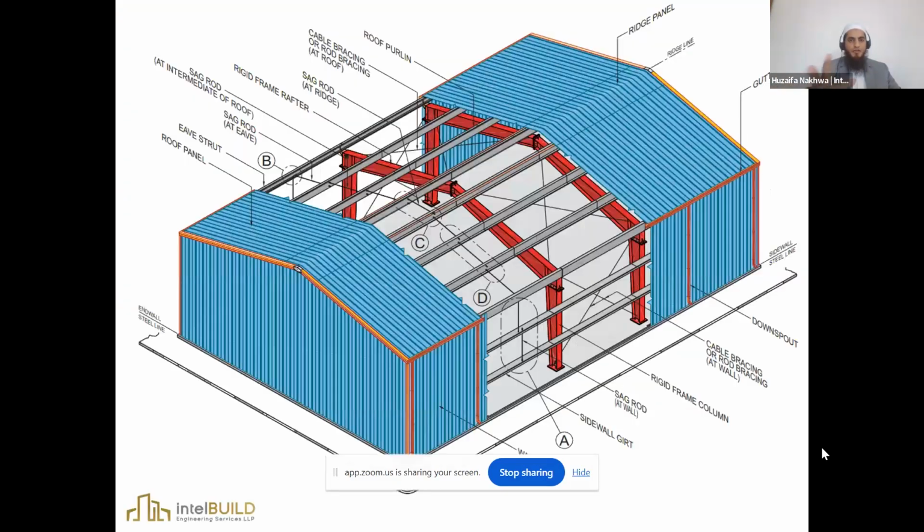Here we are describing the elements of a pre-engineered building. The frame, which is in red, is called the main frame section. The connections are end plate connections. The secondary elements are called purlins. The secondary elements are majorly cold-formed sections, because a pre-engineered building has its own elemental family, which suits the joineries properly and makes proper homogeneity among the elements.